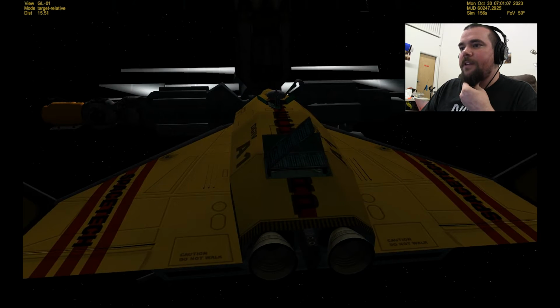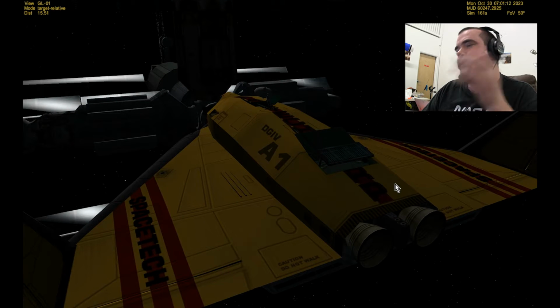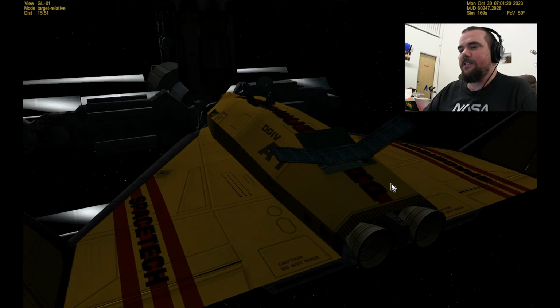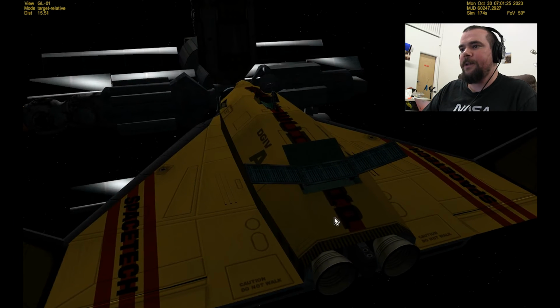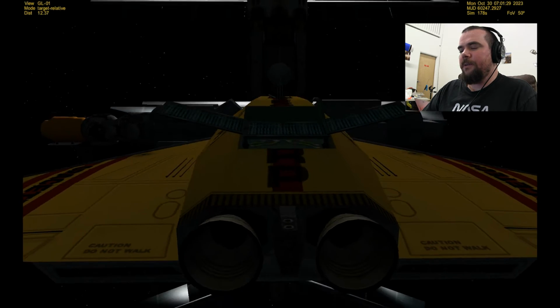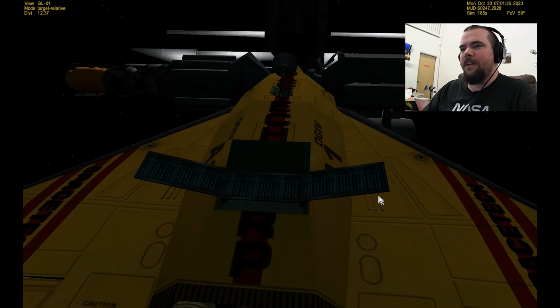The radiator is kind of interesting because normally when a spacecraft is going through space, especially on an interplanetary mission, it's just going to be sitting there baking in the sun. It gets really hot, and so it's going to be absorbing a lot of energy. So this radiator is basically a way for it to shed some of that thermal energy. It doesn't work with air, obviously. It's just infrared, but I thought it was interesting because it's a little bit like a car almost.